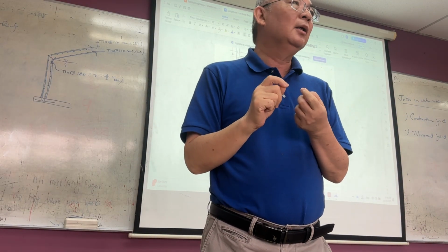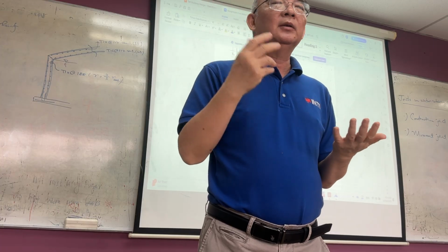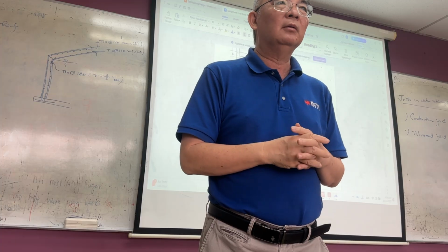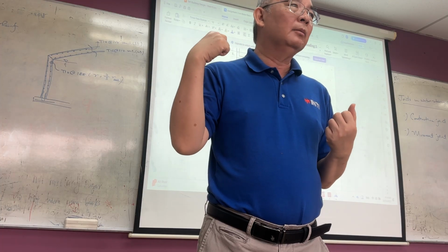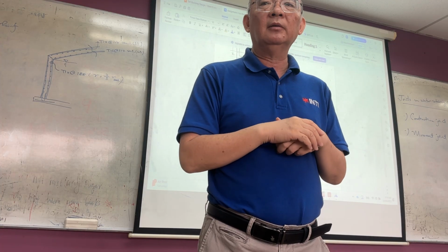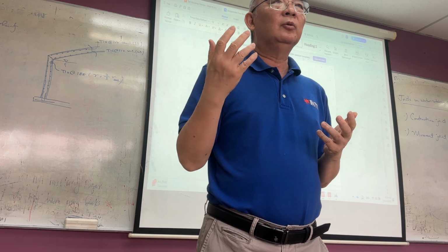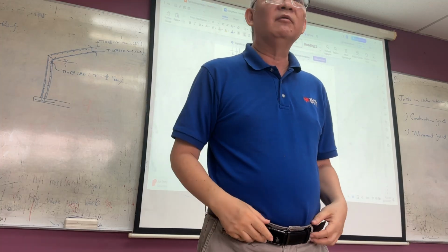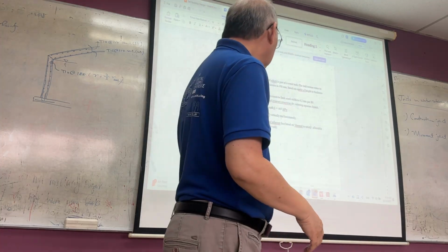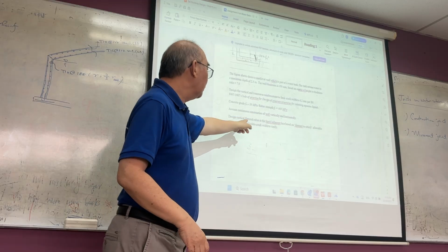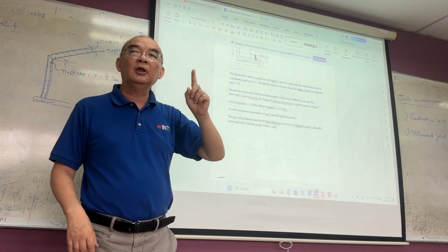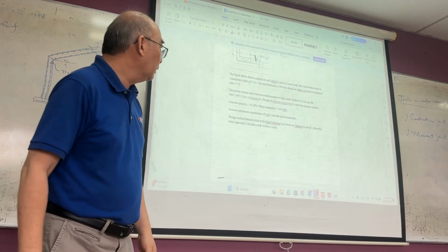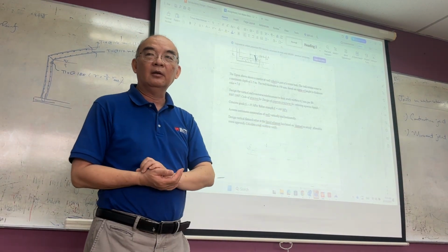To estimate it, maybe increase it by at least 50%. Or you can increase it by at least, I think the book increases it by 25%. So you can do between 25% and 50%, meaning 35% like that. Then check the deemed to satisfy approach, the allowable stress approach. Then check the allowable stress to see whether it's okay. Then calculate the crack width to verify. That's all.